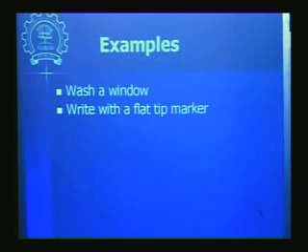It's not just tracking. If we apply only tracking controllers in these cases, will they work? Okay, we'll see what is the problem if we apply only tracking controllers. Now if the robot has to write with a flat tip marker, okay, write some number or something on the component, again it has to worry about how much force it is applying to the tip. Otherwise things will get damaged, I mean it will result in damage.